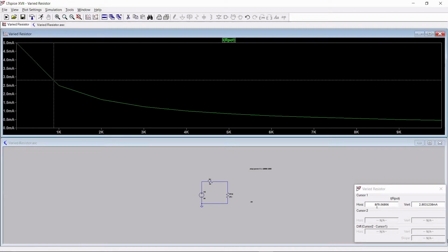And that's going to tell me that I need specifically an 879 ohm resistor. If you put that into the circuit, you could actually find that value. Or you can, since it's such a simple circuit in the first place, you could just use, sorry about that. You can combine your resistors in series and just Ohm's law that value out. Does that make sense to you, Daisy?